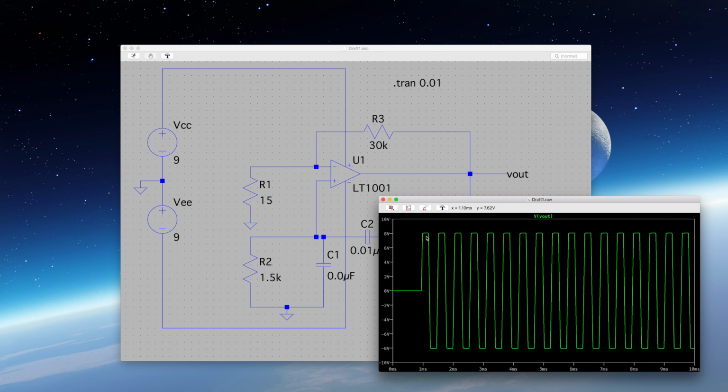And the idea is we want to get this as much of a sine wave as possible. The reason it's getting flat here is because we're hitting saturation. Remember, you have plus 9 volt for VCC, minus 9 volt for VEE. We're getting really close to that. The op-amp output will saturate, and will not give you any higher than that. So we're clipping in here. So we would like the signal to be a little lower maybe, so we don't clip as much.